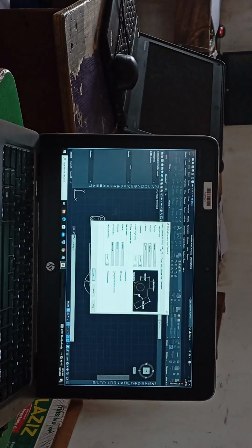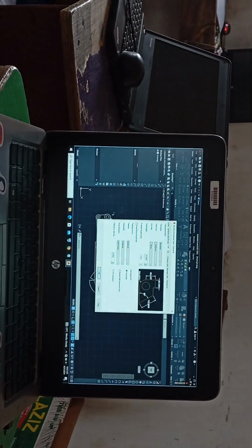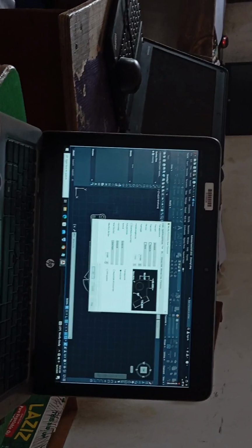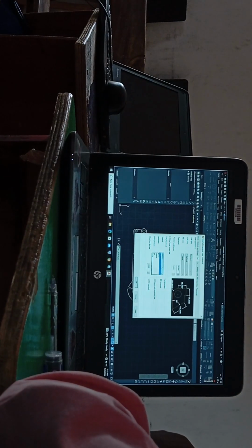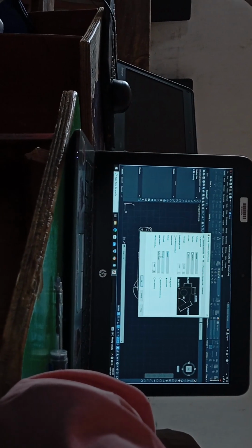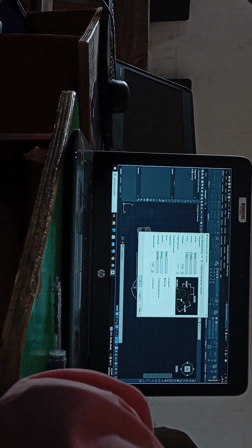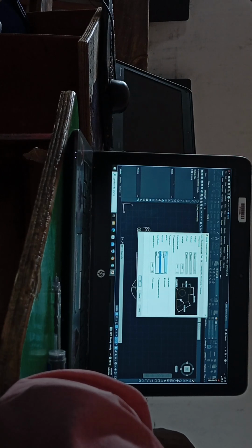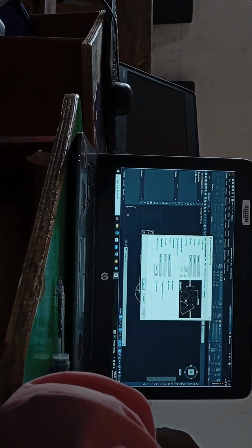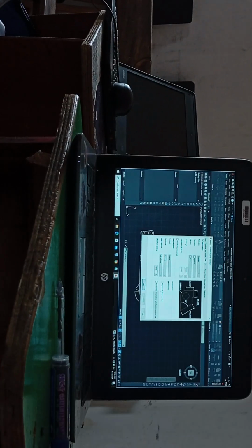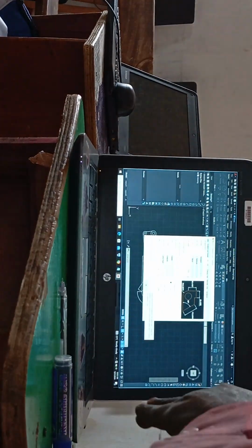I go to text again. Under text, what else do I have? Offset from dimension line. This shows how close the text is to your dimension line. I'll also change this one. I don't want it centered like it is here. I say outside, or I say above. But outside is better for me. I now say align with dimensions. If I say align with dimension, it will be vertical with the dimension line. So let me align with it.